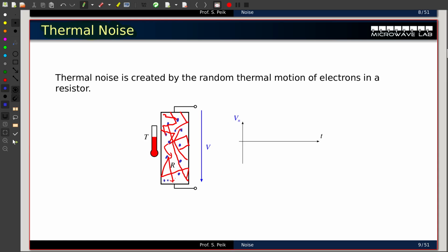And due to the motion of the electrons, you will, by accident, sometimes have many more electrons down here than you maybe have up here. When you have that case, then you have a negative charge here and a positive charge here. And that means you measure a positive voltage at the terminal. So basically I measure a voltage, maybe like this. A few microseconds later, the electrons are not down here, the electrons are up here.